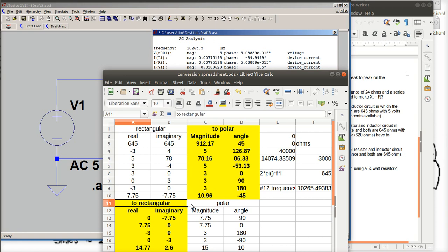Okay. So I like my answer better. Minus 45 and 135 is, oh, I know why. Because SPICE does negative current, so the positive current would be at 135. And if you're conventional, the angle would then change 180 degrees. So I get the same answer.